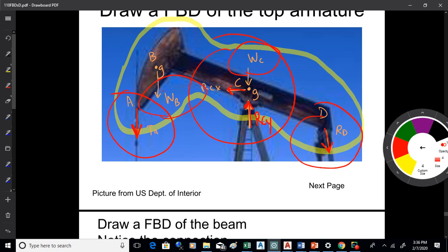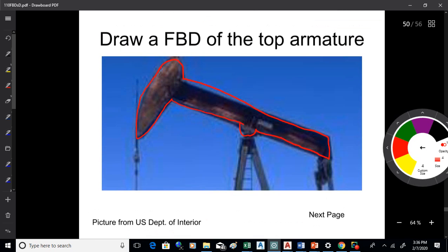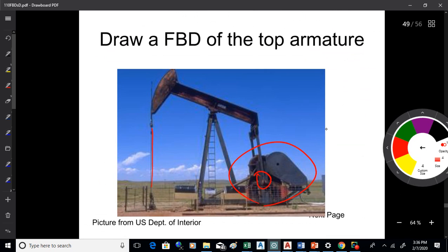With that logic, though, isn't point A and point D also pin joints? No, point A is a cable, and point D is a linkage. The linkage would be connected with a pin, but there's another pin on the other end. If you go to that page before, we call out linkages and how to handle them, on page 360 on the left top of the sketches. So I can identify that as a link. These are good questions, but what I'm seeing is there's a pin, there's a pin. That's a link. That pulls in the direction of the link. I got you. Y'all good?